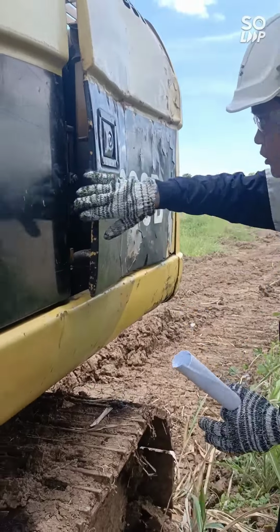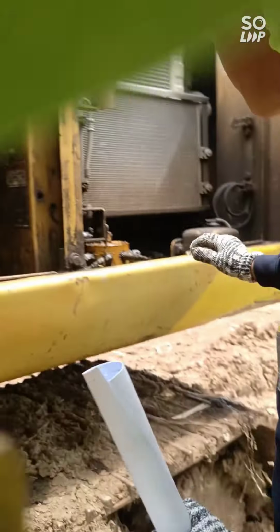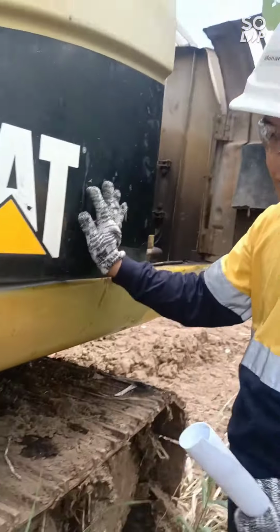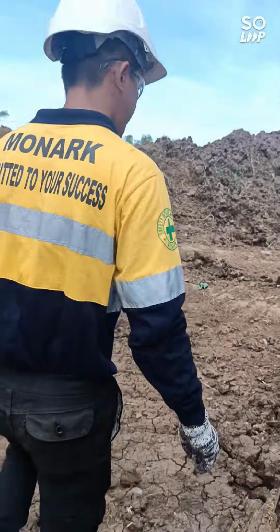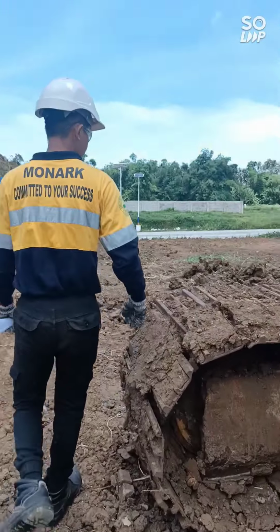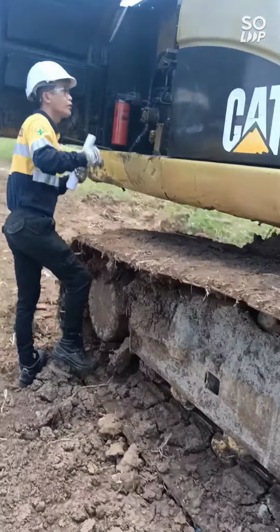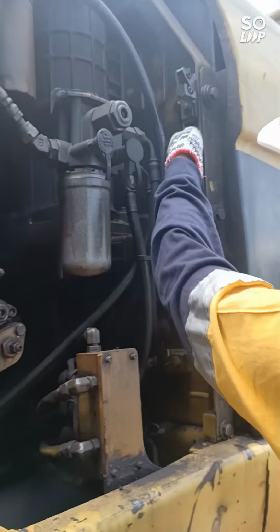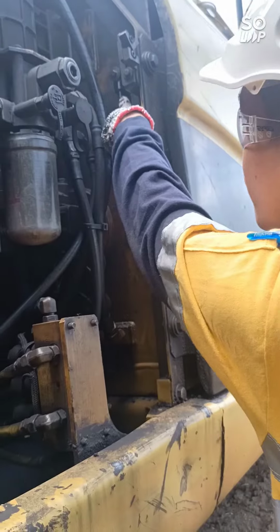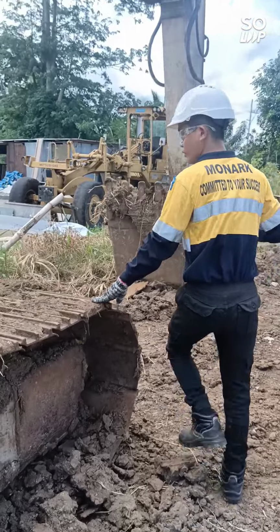And we also need to check the hydraulic oil, engine oil, and the leaks, and we perform a walk-around inspection on the machine. The hydraulic oil, if it's at a correct level, should be on the second level or up. Then we check for